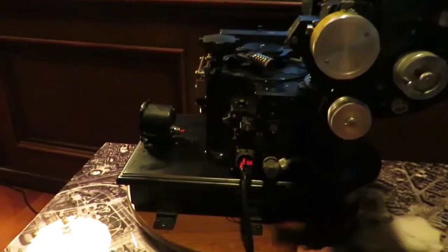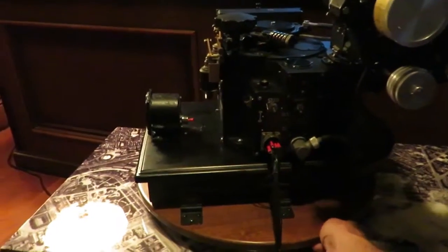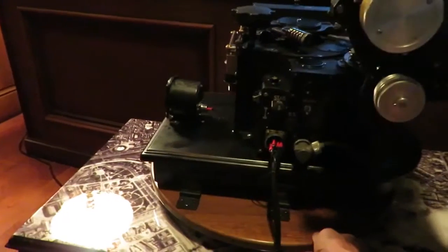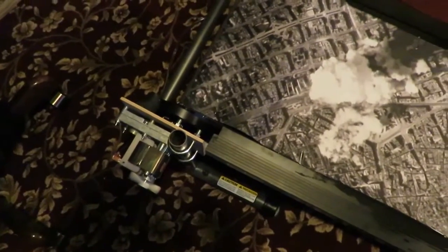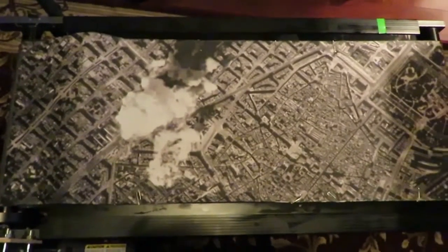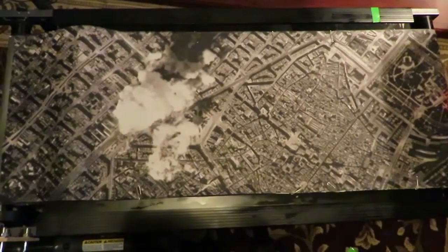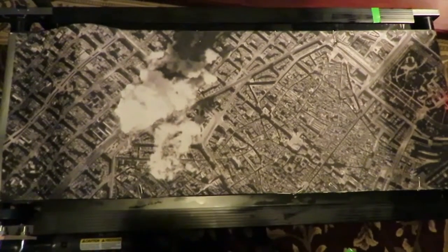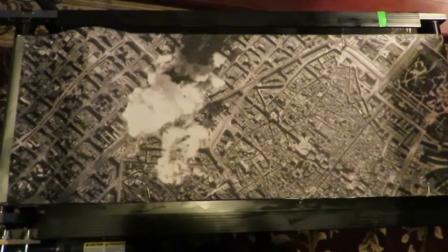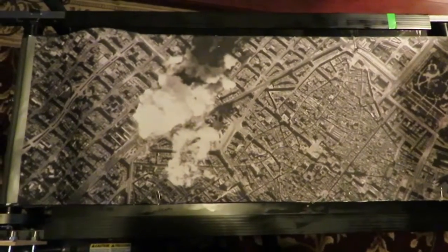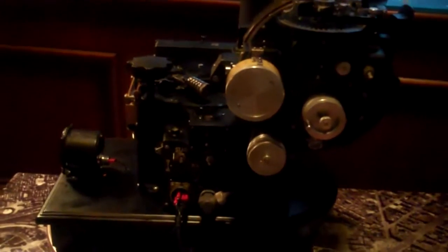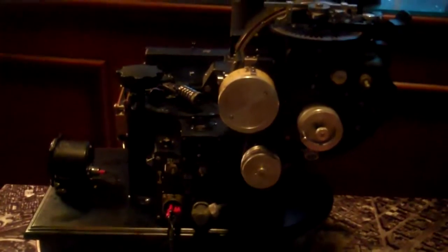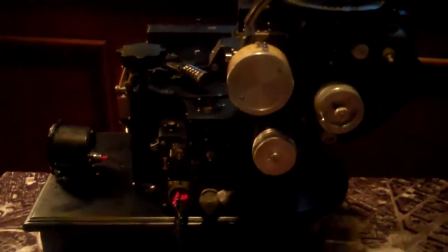The bomb sight is mounted on a turntable to simulate turning of the aircraft. A small walking treadmill has an electric motor attached, and to this was placed a poster of a bomb run. Today we will simulate a bomb run following the lead group, which has already successfully dropped bombs on the target. The stabilizer and bomb sight gyros are turned on for 3 minutes prior to activating the remainder of the bomb sight.